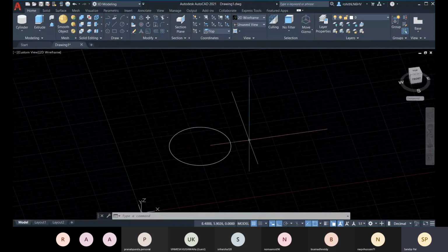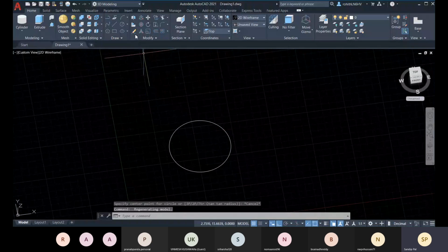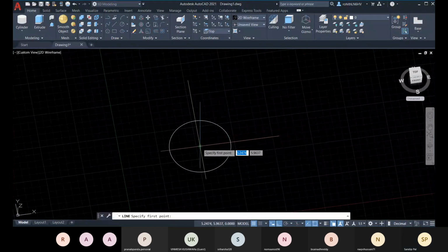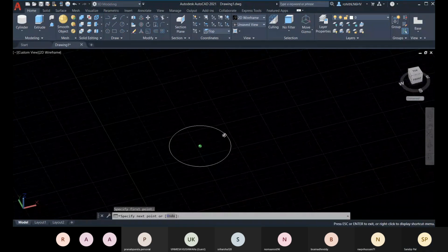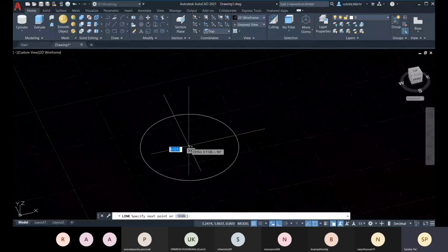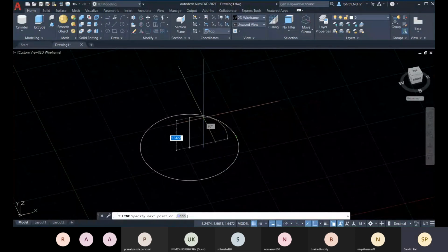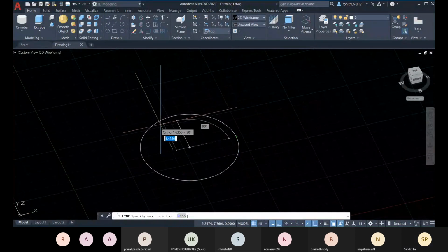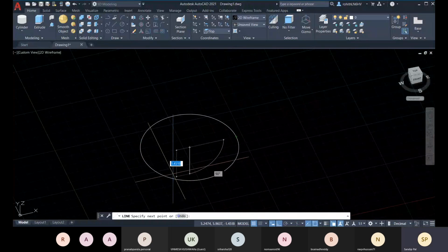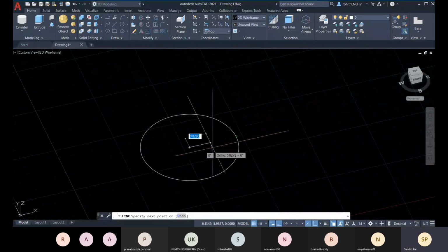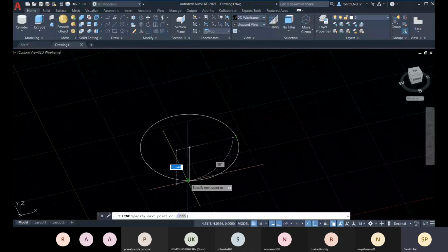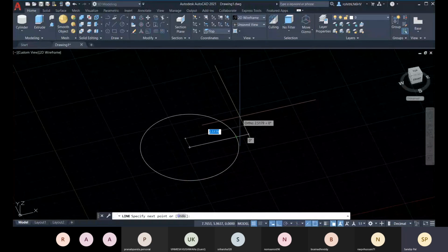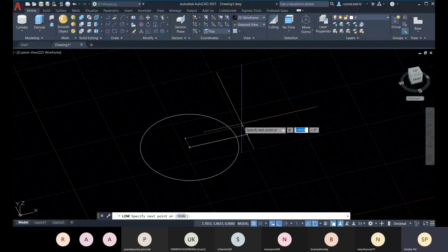Now let me create it with this formula. The center point is created, and then the radius point for your base in this XY plane you will be defining. For that you can go with the at the rate symbol, and then you can define like 2, and then at the rate 45.